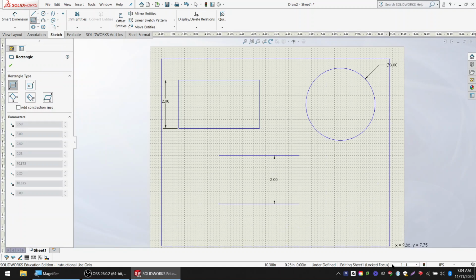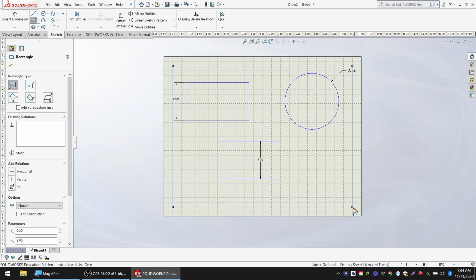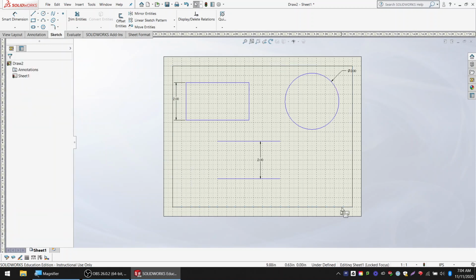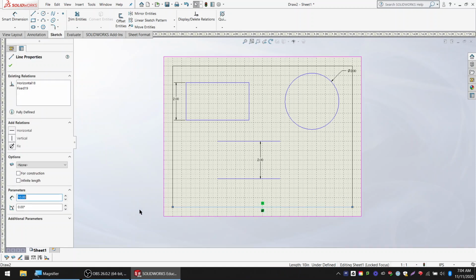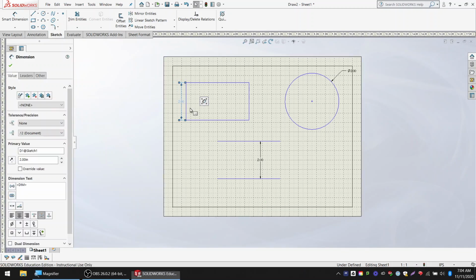If you have a border around the outside that you don't want to move at all, you can select fix in place. So when I click this, my line is going to turn black, and that's going to make it so that I cannot move that line at all. Okay, it's fixed in place. I can click on it and delete the fixed, but until I do that, it'll stay black. So any black line cannot be moved.